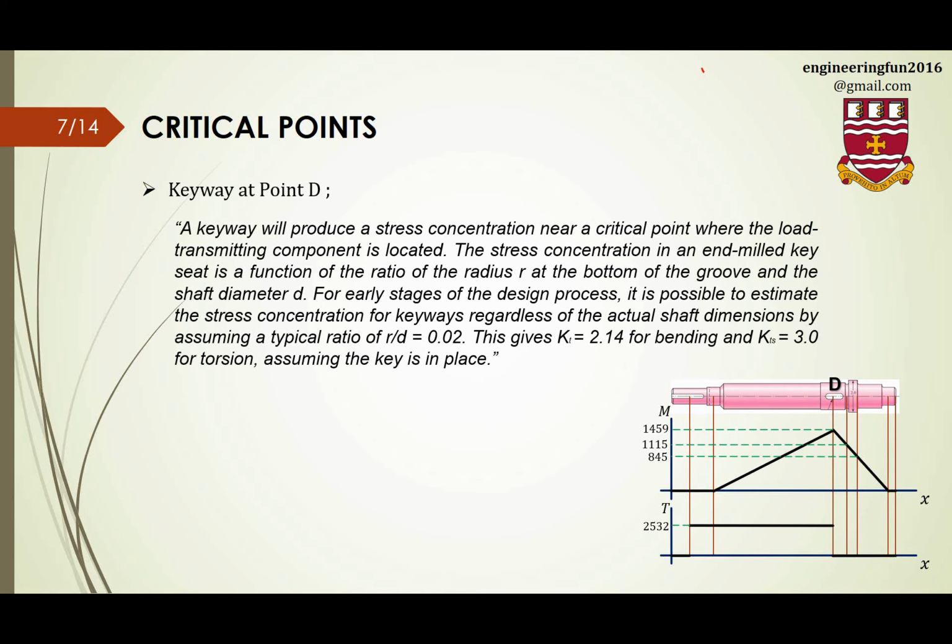This point is also a critical point for us because at this point the moment is maximum and we have torsion. So this point sounds very critical to us. Again, if I come back to Shigley's book, there's a comment again, and it says that a keyway will produce a stress concentration near a critical point where the load transmitting component is located.